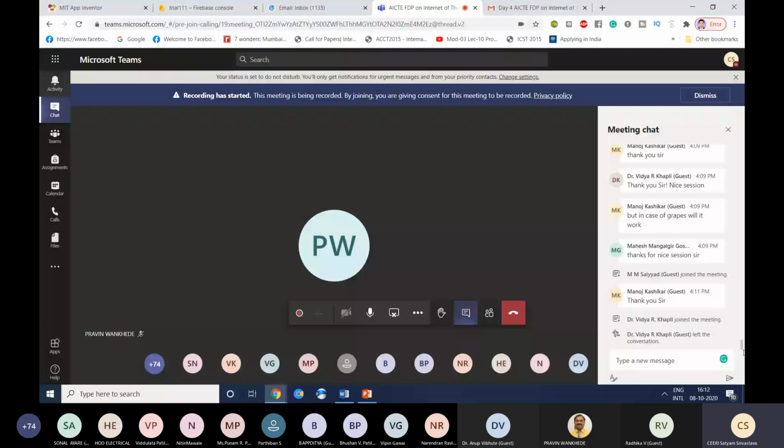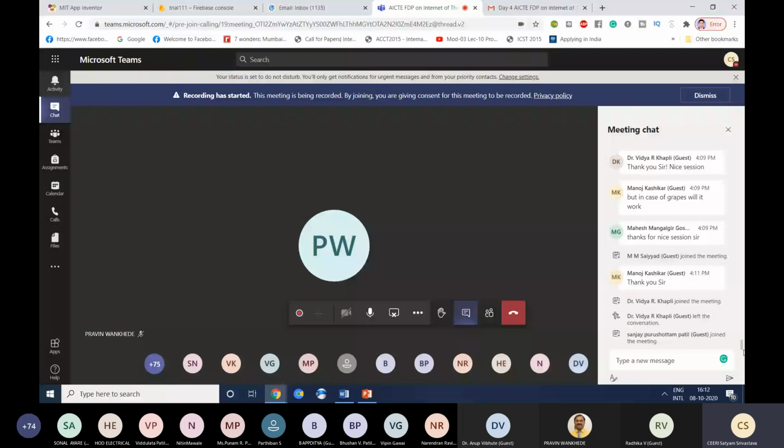In whatever device I have shown you, we have not used any kind of ready-made platforms, except in our machine vision sensing technique. We have used the ready-made Raspberry Pi computational platform. Except that, we have used our indigenous hardware and indigenous IoT enabled solutions. We developed our own indigenous IoT enabled services to send data from the device to mobile and then from mobile to cloud. So we have not used Arduino boards and these kinds of things. We have developed our own boards and our own computational platforms, and we thought about how the consumption can be kept very low.